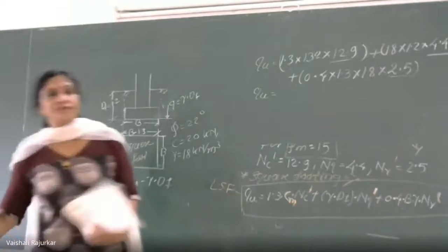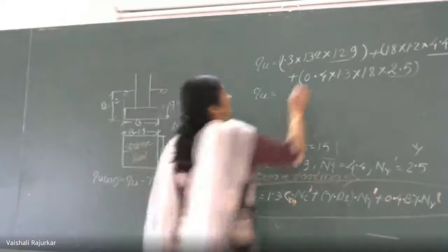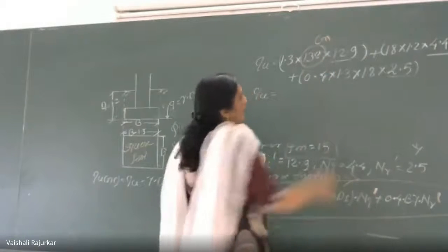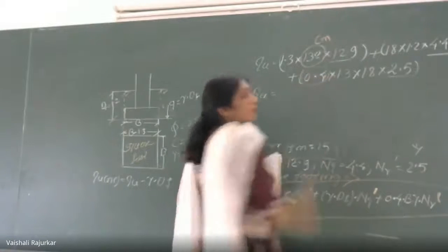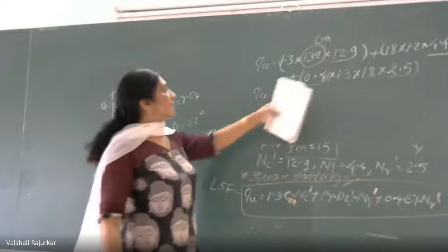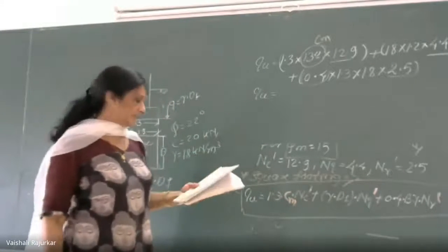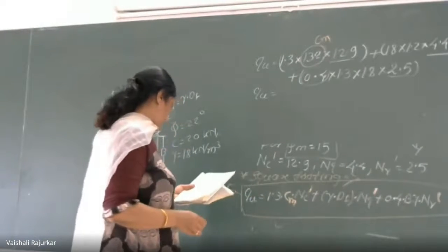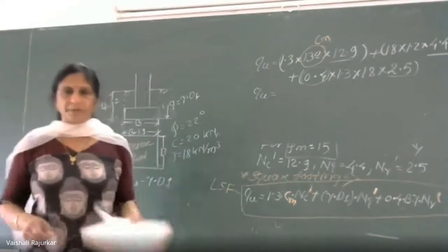In this, which modifications do you have to make? The most important modification is Cm. And one more: instead of 0.5, which is for the strip footing, in the square footing it is found to be 0.4. Then the value is obtained to be how much?